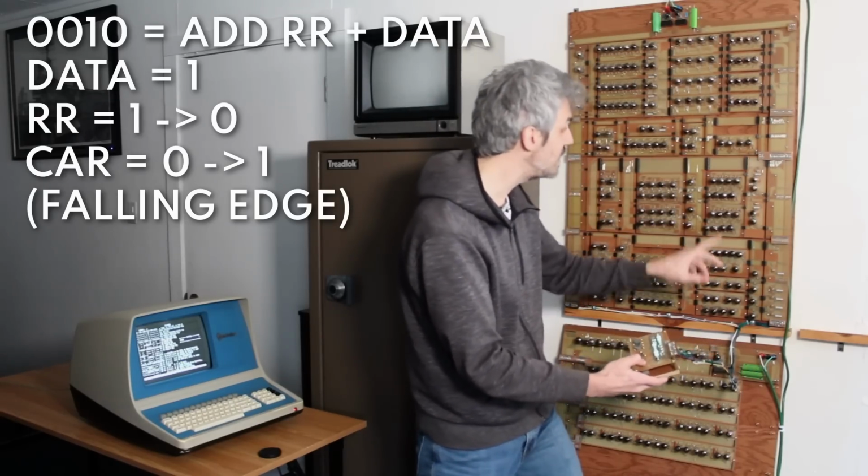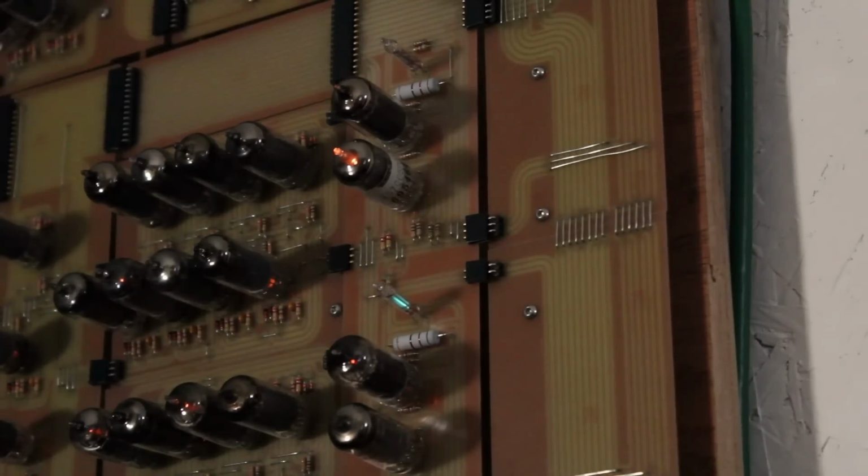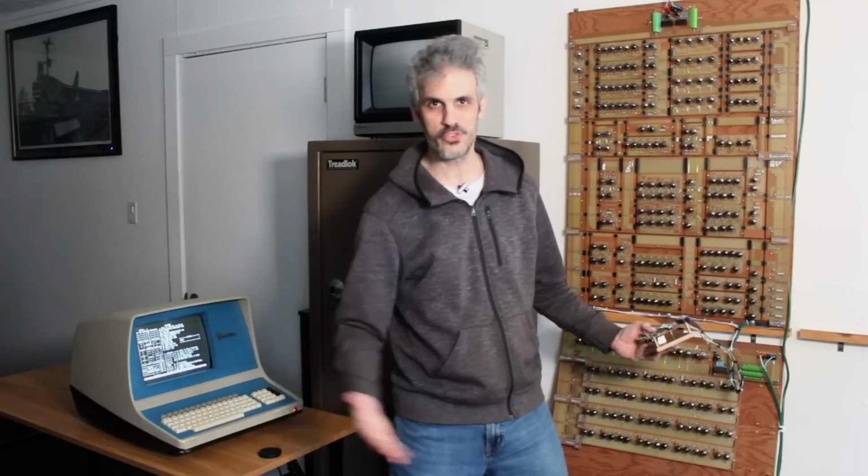But when I release it, the result register should go off and the carry register should go on. Yeah, exactly what happened. So on the falling edge of the clock, the addition occurred, or rather it latched the result of the addition into the result register and the carry register. 1 plus 1 equals 2. 2 in binary is 1, 0. This thing is working perfectly.